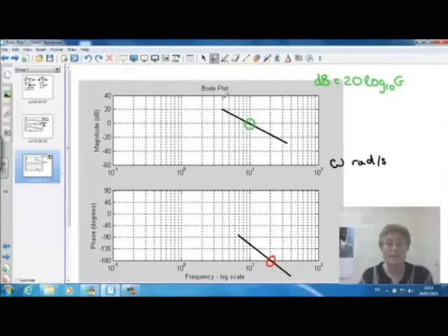And the reason for that is if we were in a condition where the gain was 0 dBs at the same time as the phase changed at the output by 180 degrees, then essentially we'd be feeding back a signal that would be 180 degrees out of phase with our input signal when our gain was still positive, and we would be adding rather than subtracting the feedback, which would give us a positive feedback condition, which would obviously give us an oscillator or an unstable amplifier.